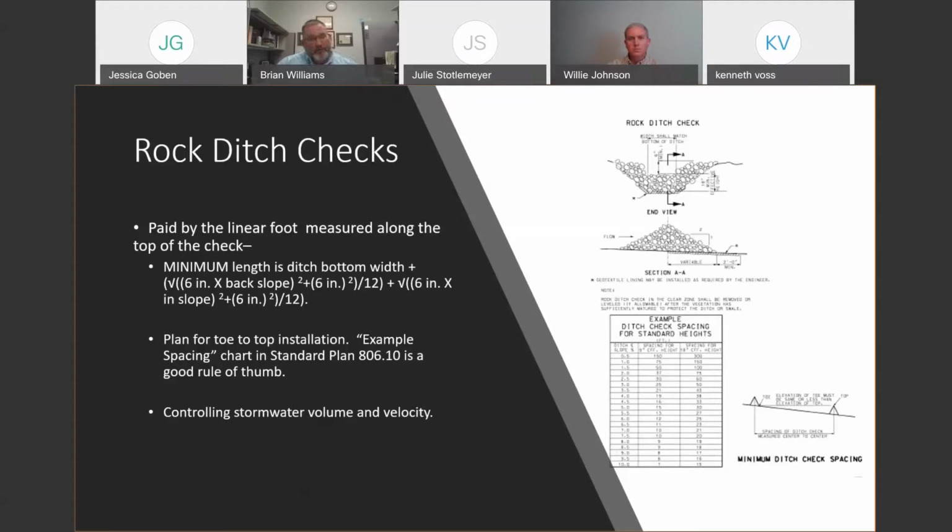Okay, because the new permit, we used to have the 2.5 milliliters per liter settleable solid limit. Well, that doesn't exist anymore in this permit. So basically, we're under the consideration of the water quality criteria. Basically, is water free from oil, scum, unsightly turbidity that is harmful to human and aquatic life. That is the water quality criteria from the Missouri Clean Water Law.